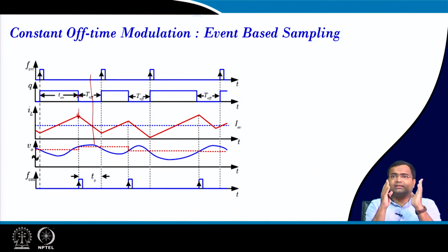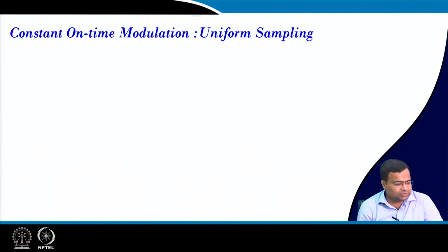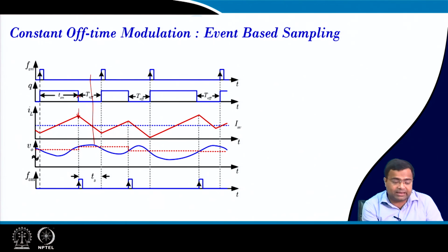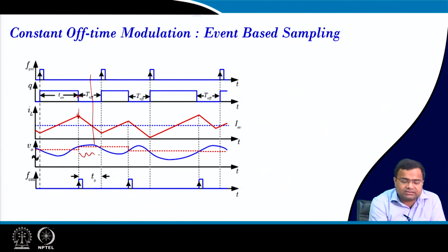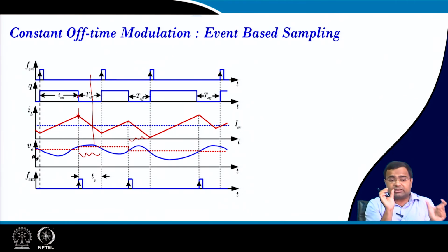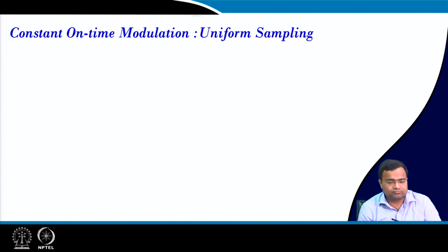Particularly, we want to highlight the fixed frequency modulation. If one understands it thoroughly, then he may try the variable frequency for going into detail. So event based sampling will synchronize with the event rather than time. You will eventually get one sample per cycle, and you can see there is always a fixed interval between the sampling point and the on pulse, the trigger pulse. So the delay will be fixed because you are sampling with respect to an event.